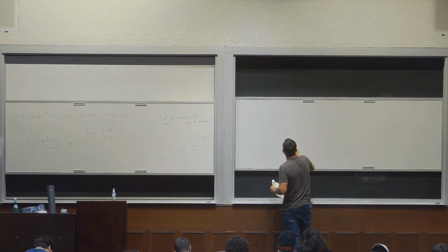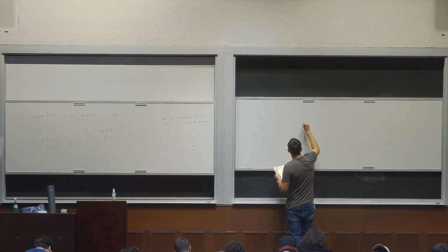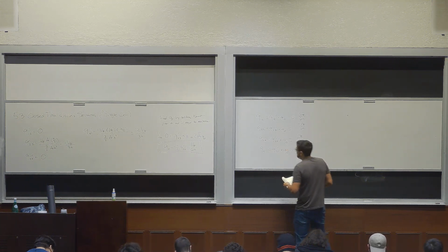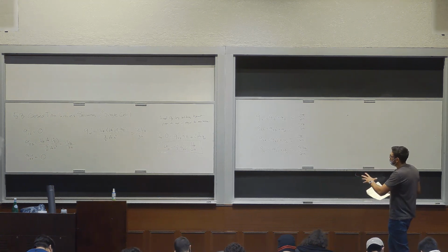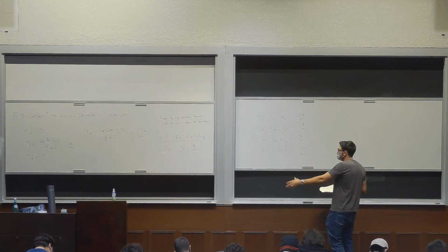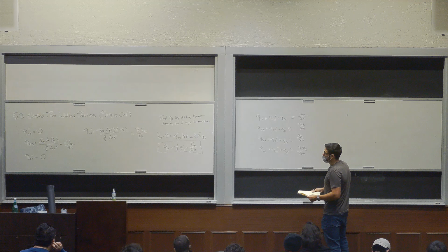We have all the values over there. It's VZ over 6H, negative VZ over 6H, VZ over 6H, and 5 VZ over 6H. At this point, a lot of these problems will be done. They just want you to find the shear flow and find the maximum stress. So we would just divide by a thickness at a certain location. We'd be done. This problem wants us to find the shear center.